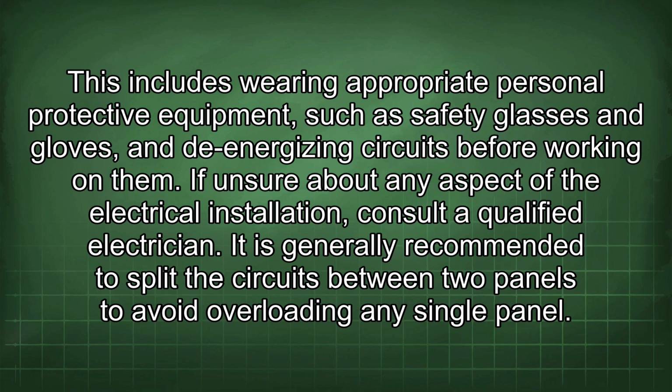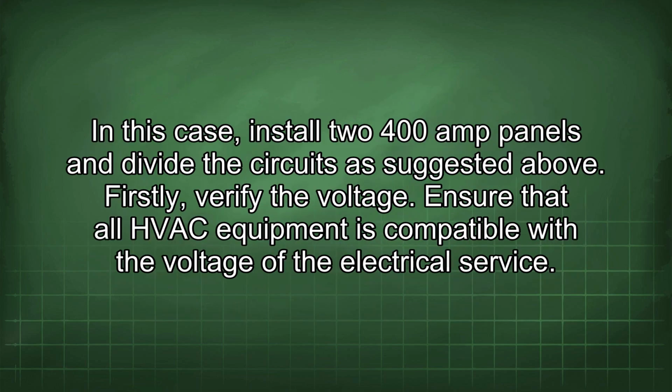It is generally recommended to split the circuits between two panels to avoid overloading any single panel. In this case, install two 400 amp panels and divide the circuits as suggested above.